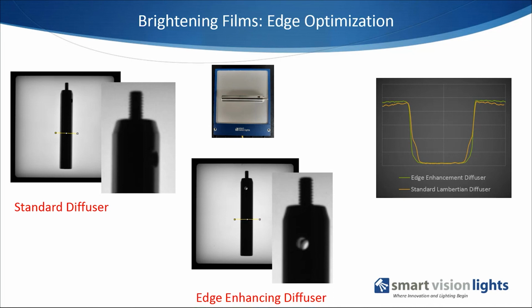And you can see from the graph the sharpness and the steepness with the diffuser and film there that's lending to the effects I described in the images themselves. So make sure that your backlights are coming from a quality manufacturer and that you're using these kind of films, or that the manufacturer is making backlights with these kind of films, because they will affect your performance, and not all backlights and light sources are equal.